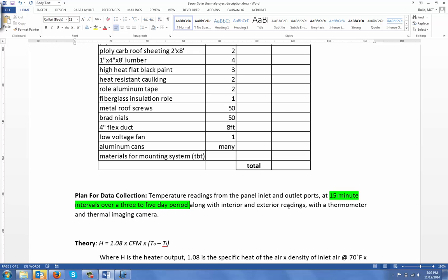And I'm thinking that I would love to see interior, both intake and exhaust manifolds. So you'll have 3 separate readings. You'll have just the outside air temp, intake manifold, which is essentially the temperature in the room, and then your exhaust manifold. I think that's probably, because that's going to give you your delta T. Right. That's going to give you your power